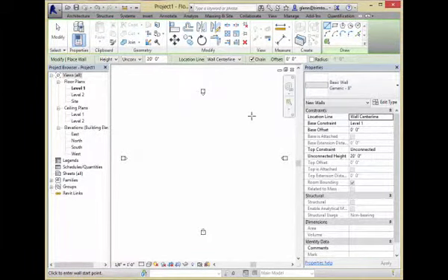You'll notice even before I place some walls, there are some options that are available. One is the height of the wall over here, then there's the location center line. That's going to affect the instances I place down. Okay. You can also see those properties over here in the properties column. But let's start by just placing some walls.